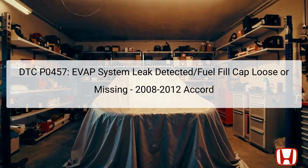The Diagnostic Trouble Code DTC P0457 signals an issue within the EVAP, or Evaporative Emission Control System, specifically indicating a leak or a loose, missing fuel fill cap. The EVAP system is designed to prevent fuel vapors from escaping into the environment, capturing these vapors and directing them back to the engine for combustion.